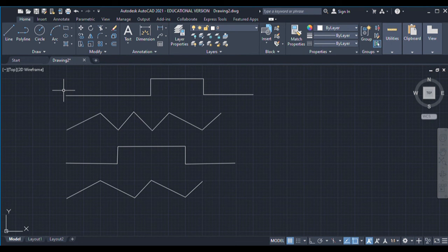So that was one of the methods of how you can select your object or your drawing. The other one is called the solid window selection, where you click and leave your mouse, then you move like that. Now I want you to observe something here: every line or every part of the line that has been highlighted is going to be selected.